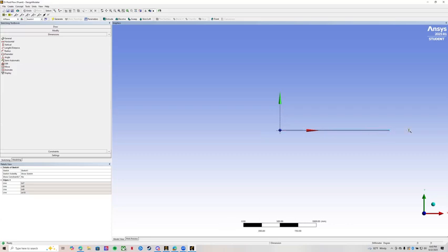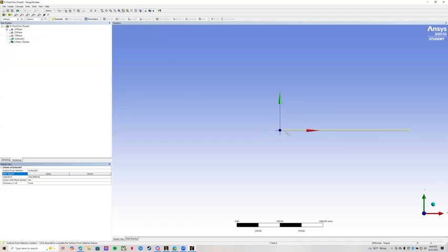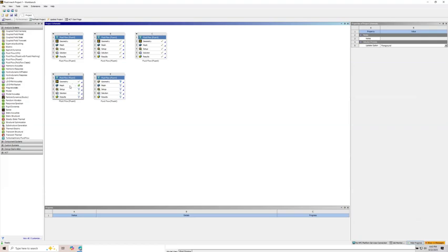So we're going to zoom in here. As you can see, we have our dimensions. Go ahead and we're going to pick box select. We're going to select our body here, our sketch. What we need first is to make a surface, and we're going to select our sketch here. We're going to apply it as our base object and generate our body here. All right, so now that we've done that, we're going to exit. We're going to just close this part down here for now. And so now we have our geometry.